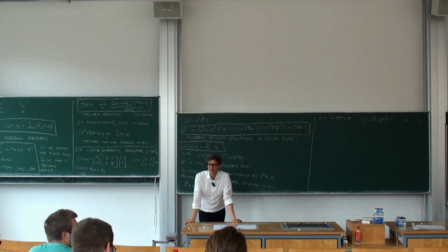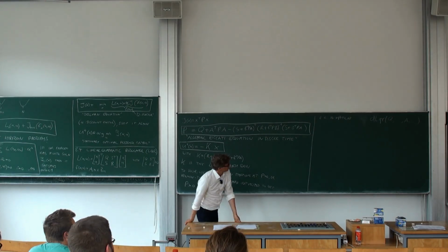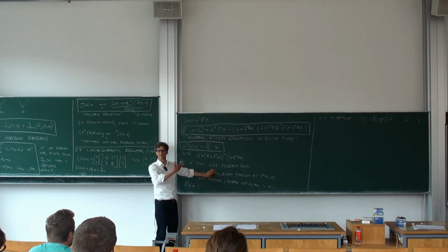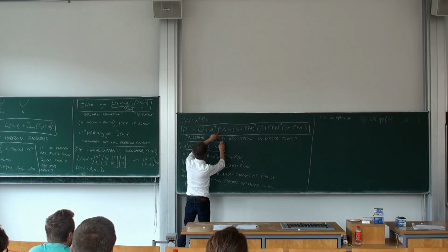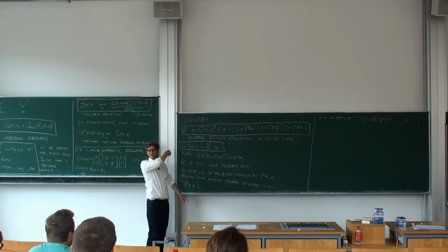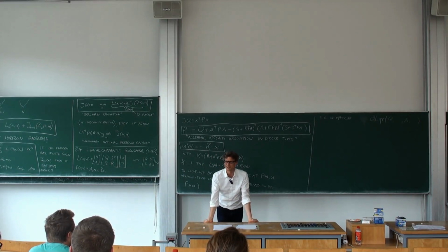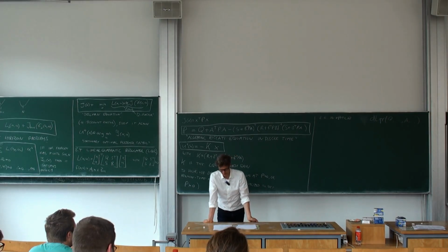Yes, please. Since this is the Riccati equation, I heard the term Riccati iteration. Is that like solving the... I think probably when I say this DP recursion, if you do it for linear quadratic problems, you could call that a Riccati iteration, where you have the index k here and the index k plus 1 here in order to iterate. That's what I would think it would mean, but maybe we should look at the literature where you found that.